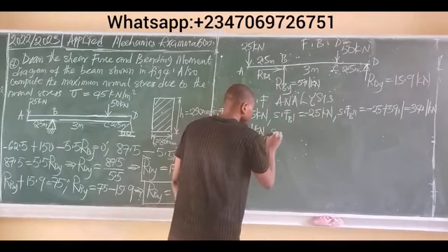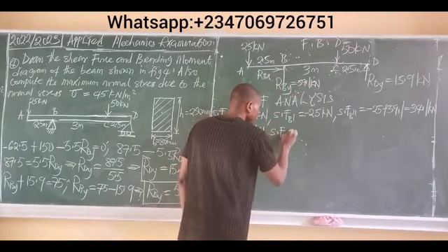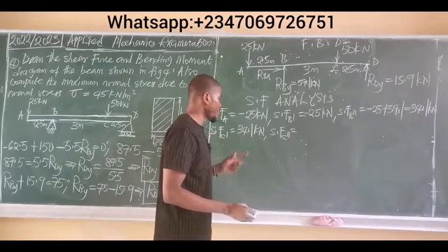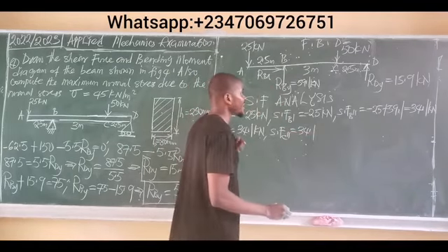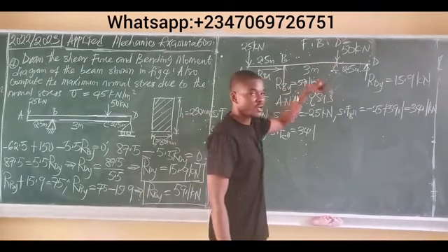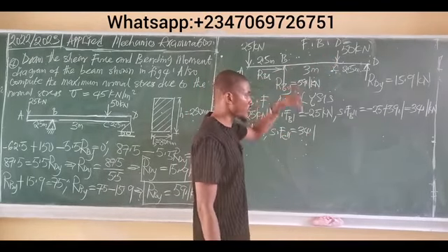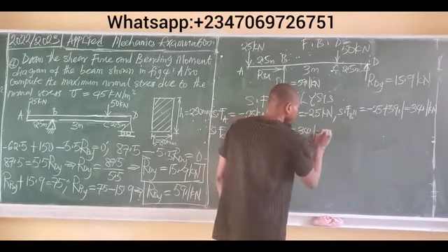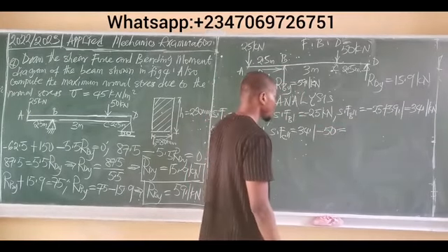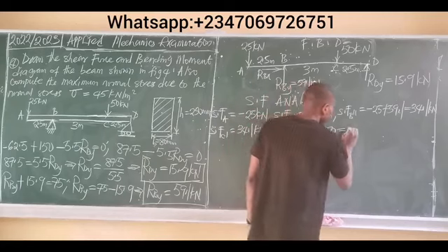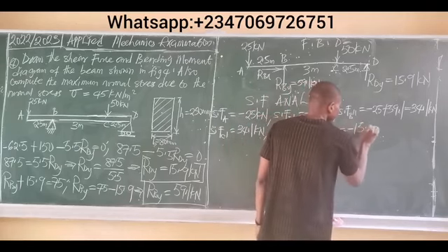So this becomes shear force C prime prime, which means finally at point C, the 34.1 kilonewtons force now encounters a downward force of what? 50 kilonewtons. Now, since this force is coming downwards, it becomes minus 50. And 34.1 minus 50 gives us minus 15.9